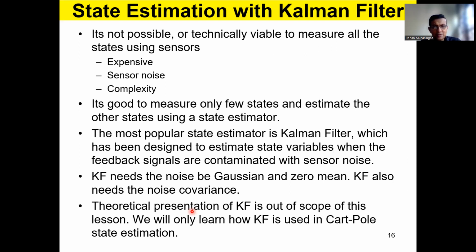There's nothing I can do more than what you already have. The sensor signal is already good. Go ahead. It will estimate something which is very, very close to the sensor signal. Because when you tell the Kalman filter the noise covariance, and the covariance is a very, very small value, the Kalman filter understands this is a very high quality sensor.